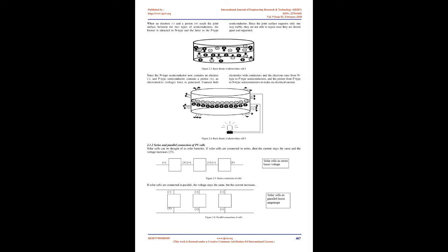As part of an operational and maintenance program, the PR may be used to identify the existence of performance issues. Chang Yingpin and Shencheng Huang [10] presented a paper about the effects of solar module installing angles on the output power. In their paper they discussed that the output power increment of photovoltaic cells is mainly based on two factors. One is decreasing the cell module temperature and the other is increasing the cell's received solar illumination intensity. The former can be simply achieved by maintaining a proper radiating space between the modules and the ground. The latter is more complicated. One needs to consider the installation of cell modules and then the maximum power output which can be derived.